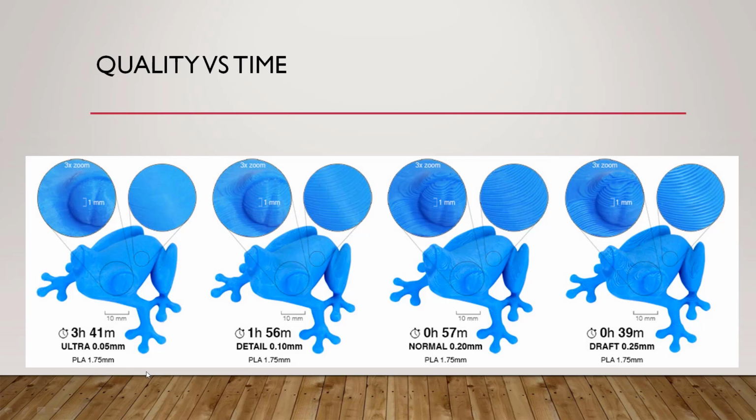But if you take layer height 0.10 mm, you can see the time has been drastically reduced. In the earlier model it was 3 hours 41 minutes and here it is 1 hour 56. So the time has drastically reduced because of the layer height. Layer height is double, so time is less. Again, if you zoom in, you can see the fineness of the first one is more than the second one. The second one looks slightly rough, and you can see one layer after another.